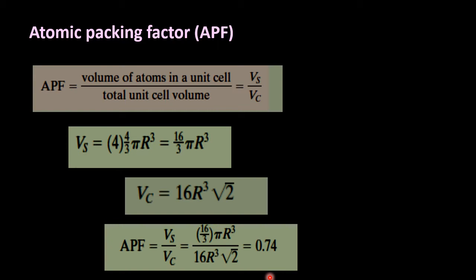This is the maximum packing factor possible for spheres all having the same diameter. Metals typically have a relatively large atomic packing factor to maximize the shielding provided by free electron clouds, as we know the free electrons which form the cloud are present within the metallic crystal structure.